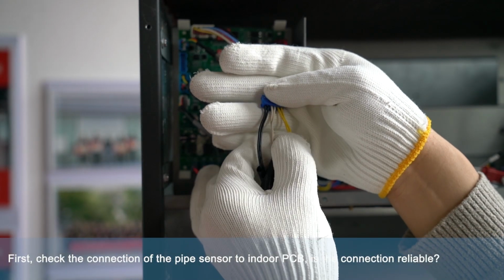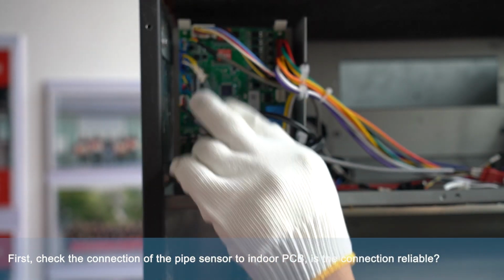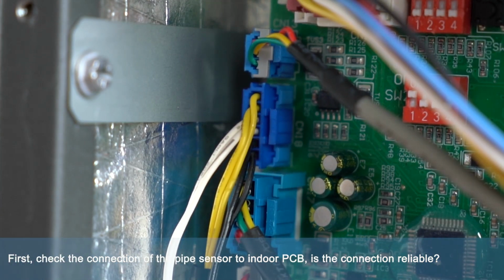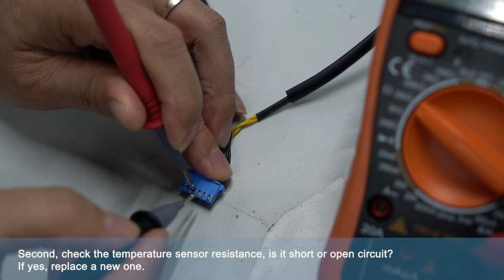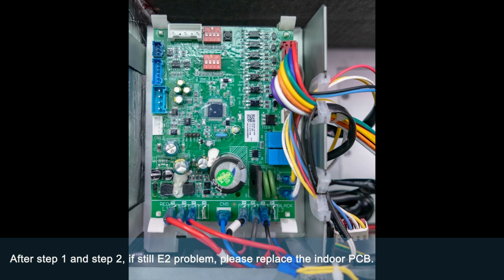First, check the connection of the pipe sensor to the indoor PCB. Is the connection reliable? Second, check the temperature sensor resistance. Is it short or open circuit? If yes, replace with a new one. After step 1 and step 2, if still E2 problem, please replace the indoor PCB.